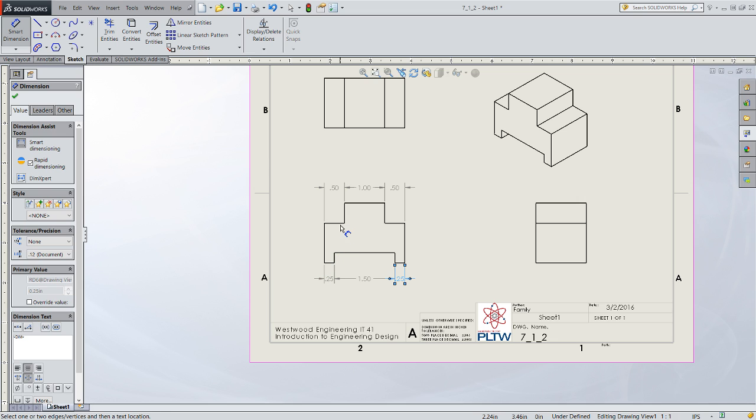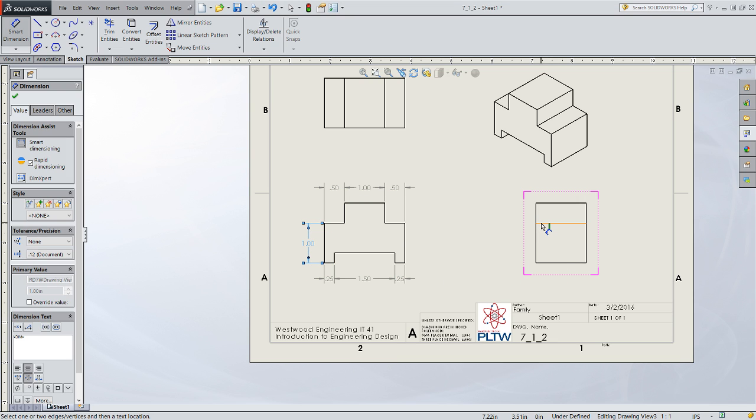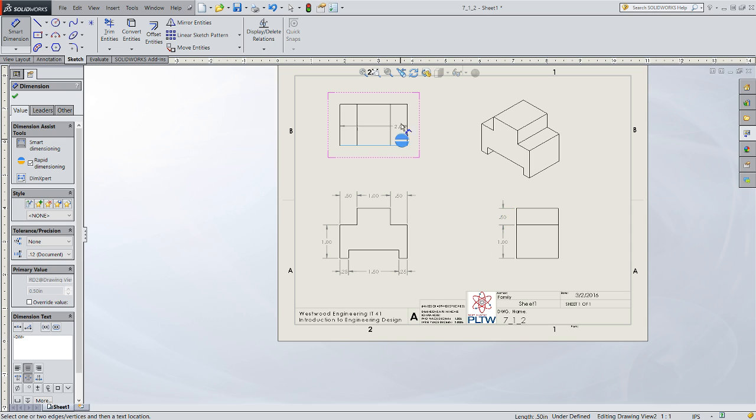Now, because it's not patently obvious that these two are collinear or coplanar, however you want to view it, I'm going to go ahead and give a dimension on this side, which is a little bit non-standard, because I can't see that hidden line on this side. And I'll go ahead and dimension the same opposite side here, and then the overall height of the object. The depth is very straightforward,